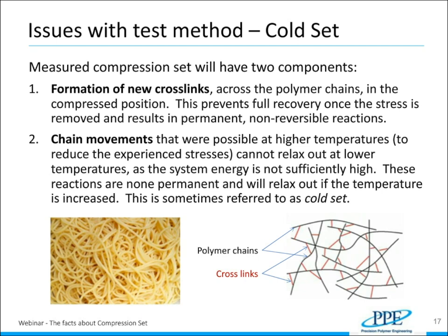Some of you might also have heard it referred to as the Monday morning effect, where machinery that's been shut down and cooled over the weekend then leaks or weeps slightly when it's turned back on Monday, until the whole thing warms up again, and all the seals now have the energy to start moving and start reacting to the applied pressures and forces.